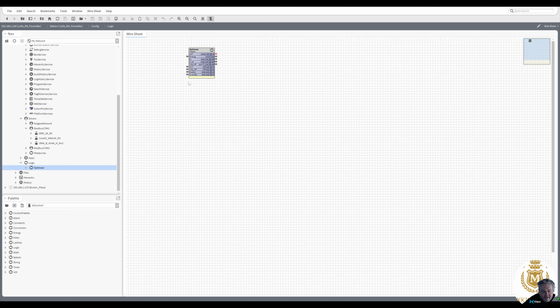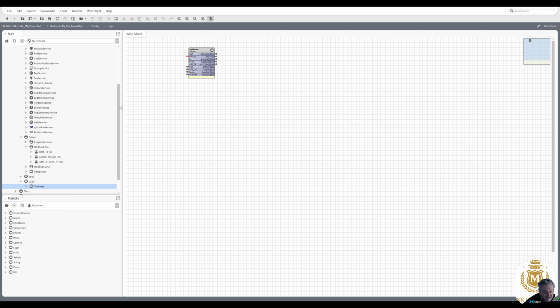And then I've got a temperature sensor for my average room temperature, which is reading from a Core IO40 multi, which I've got installed with a temperature sensor on universal input 1. So we've got the temperature here of the physical cabin that I'm in. So we're putting that to there, but I've got no outside air, so let's just do that.